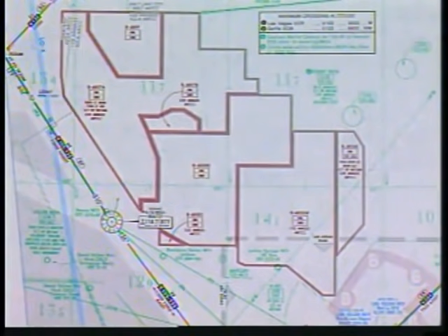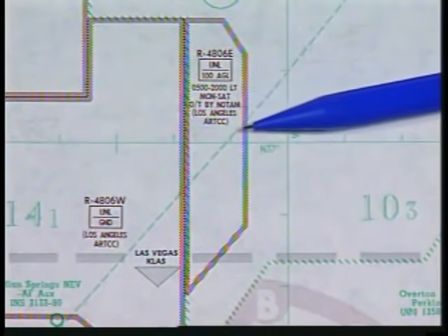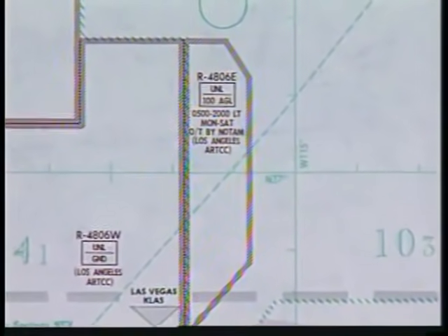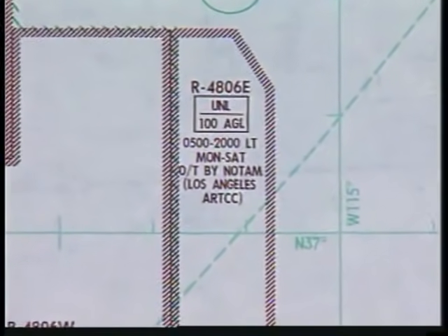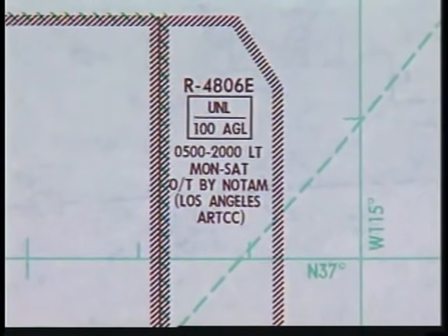Special use airspace is shown in green and magenta and is designated for use whenever aircraft activities require airspace operational limitations. For example, a restricted area is outlined with magenta diagonal slashes. The identifier, affected altitudes, times of activity, and controlling agency are shown. If space is limited, this information is printed either adjacent to the area or will be found on the front or back panel in the section entitled Special Use Airspace.